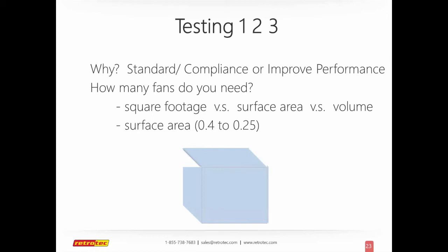The thing we're trying to focus on is to improve the performance. So the type of test we're setting up is very basic: where's my leakage? I can quantify the numbers and then repeat the test to confirm that it got better. So it really isn't an ASTM or an Army Corps type of standard, even though I would be familiar with those as guidance as to which way you need to go.